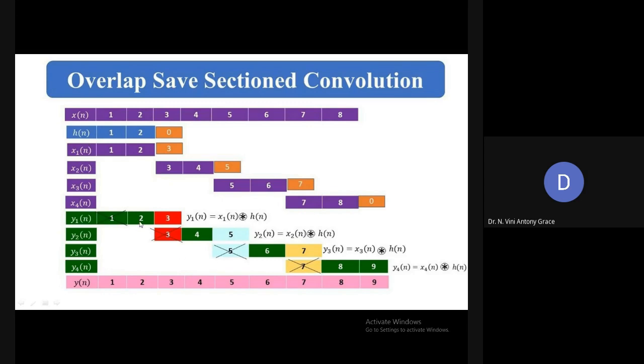Once you follow the matrix method to find circular convolution, since the input has 3 samples, every output is going to have 3 samples. So I'm writing all the 3 samples here. And as in the statement, n2 minus 1 samples overlap with each other, so output samples are also overlapped.